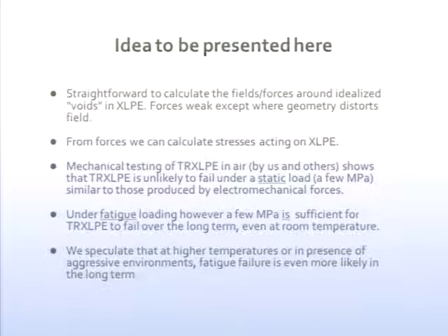We've done mechanical testing of the polyethylene in air, and so have other people. And that shows that the polyethylene is unlikely to fail under a static load of a few megapascals, similar to those produced by mechanical forces. So at first glance, when you do the experiment of putting the material under stress, you reach the conclusion that this school of thought, which says it's an electromechanical phenomenon, you're inclined to dismiss.